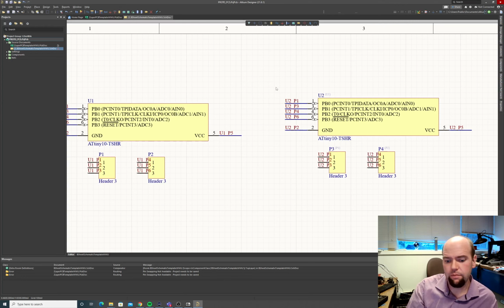So if you're doing a regulator, like a switching regulator, a buck or a boost regulator, the feedback circuits on those should all be implemented on your actual PCB, because if you try to implement a feedback network on a boost regulator outside the PCB, it's going to have enormous noise. The traces will be way too big, the distance way too big. So quite often when you're doing these little prototype pieces, you have to implement some of the circuit on the actual part itself. So we're going to do that here.